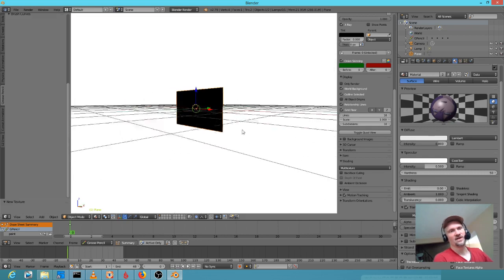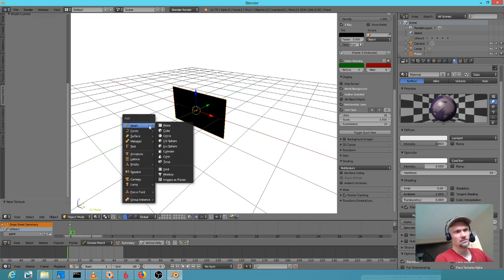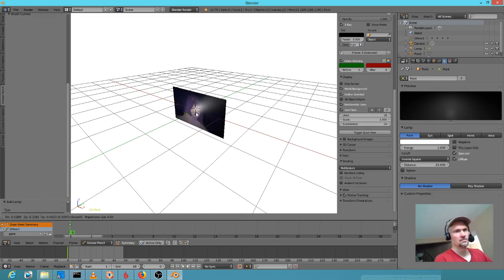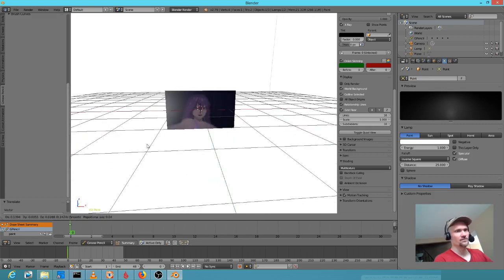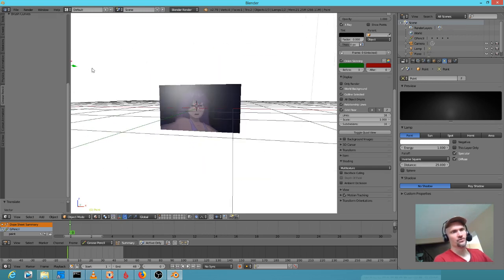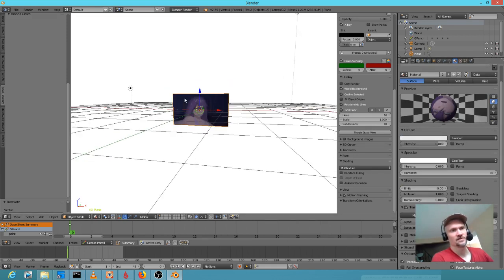Now we want to get that effect of being able to illuminate our 2D animated character, right? Well, no problem. Just add a light. And look what happens. Okay, it really is just that simple. Now you're going to have some hokiness here in regard to the specular glare, obviously. So what does that tell you? Well, that tells you to go back to your material and turn the specular intensity off. We don't want specular intensity for this application, for this material.